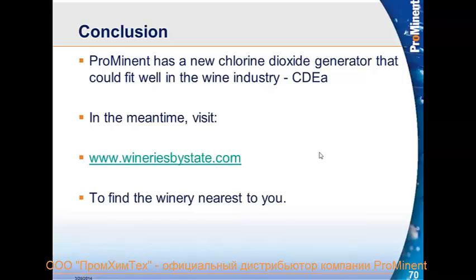Another question we have here, are there wastewater discharge regulations on chlorine dioxide? Yes, there is. Off the top of my head, there's one for chlorine dioxide and one for chloride. One is 1 ppm and the other is 0.8 ppm. And this was from Tom. I'm not sure exactly which is which, but it's one of the two. But yes, there are EPA regulations for wastewater. So be sure to check with your state. That might be different from state to state too.